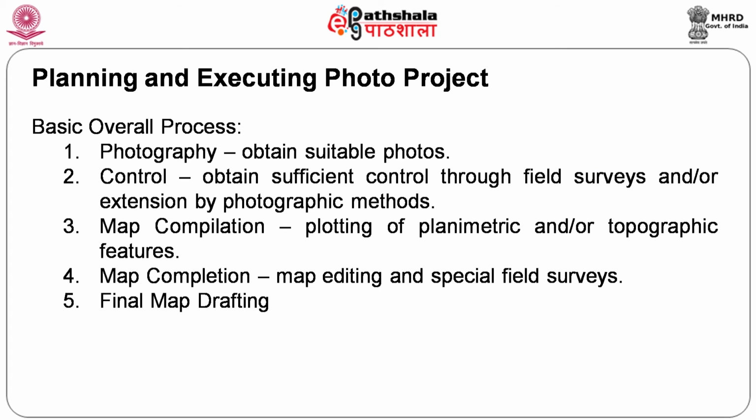We will see the details a little later. At the time of photographing itself, we will be getting the detail. So, that detail, if I have it, I know its position because I have placed it there. I have kept the control there. Then I can identify and understand, and if I know its XY, automatically I will be in a position to get the XY of the aerial photograph.